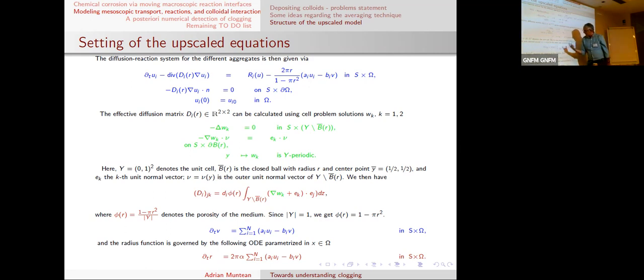So that's what I wanted to say. This diffusion coefficient has two components, the porosity and the rest. The engineering world calls the rest tortuosity. What is the tortuosity? It is a concept which nobody tells me what it is. They tell you, well, you can't really measure it, but it exists. Sometimes they tell you it's a number, but in fact it's a tensor, right? If you assume some regularity, some arrangement of the microstructure, you can compute it.